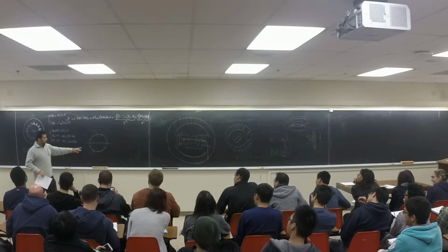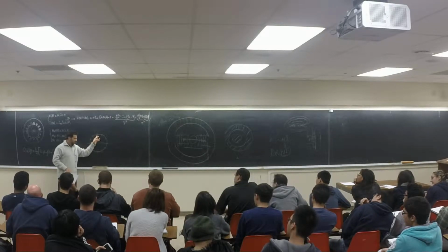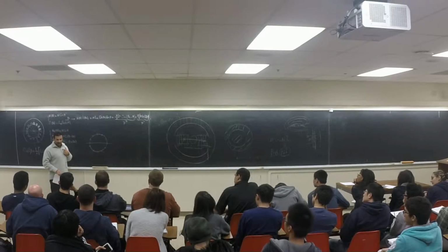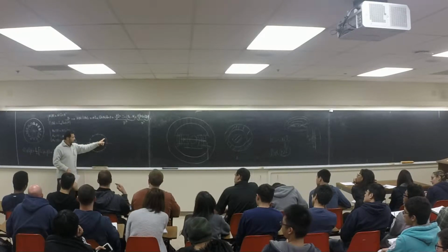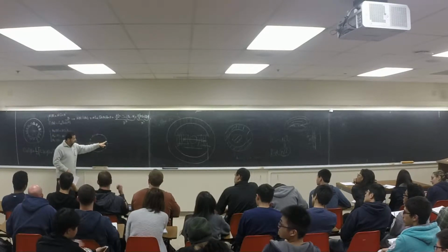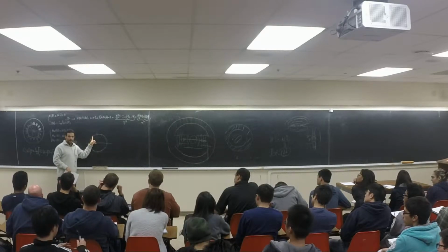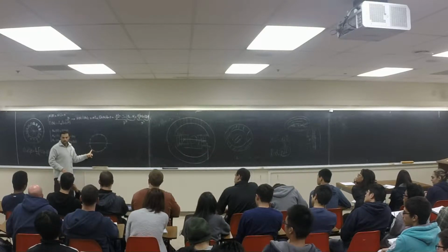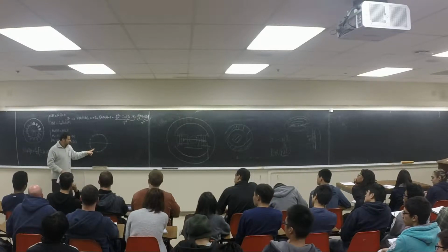Like this, right? So for phase A, I'm going to put 0 winding here, right? 0 winding here, right? The maximum numbers here, right? So this is sinusoid, you know, we talked about it. For phase B, I'm saying, okay, the 0 should start at where? 120, is it? 1, 2, 3, 4. I'm going to put 0 winding here, right? 90 degree after this, I'm going to put the maximum number after it. 1, 2, 3, 4. I'm going to put in this slot the maximum number. For phase C, 1, 2, 3, 4. I'm going to put 0 here.